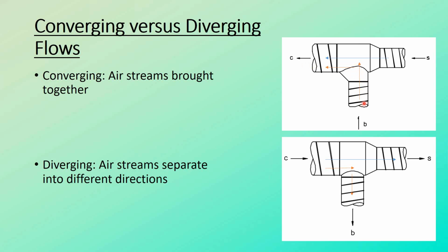You're going to see these different types of fittings on the static pressure spreadsheet. If it's a supply and you're calculating your critical run going straight, and there's a tap off to the side, this is a diverging Y. If you're going straight through, it's a diverging Y main, because you're not taking the branch. And if you're looking at your critical run that comes out on the shoe tap, this would be a diverging Y branch, so you're taking the branch.